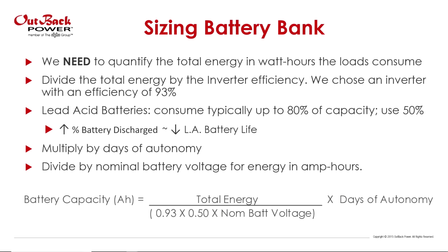So we need to consider also our 2 days of autonomy. That means that we'll need twice the batteries. So that's something also to consider when you think about the days of autonomy that you want, because the cost of that could increase significantly.